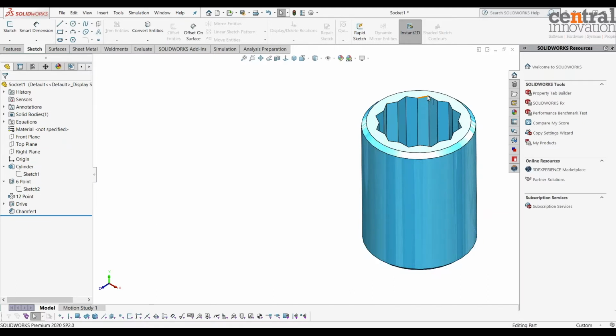can be tricky here. If you increase one of the dimensions, this thickness will get narrower. For example, if you change the cross flat dimension to 1 inch or more, it is in fact useless. So we're going to address this problem in the design table as well. Let's go and start with the design table.